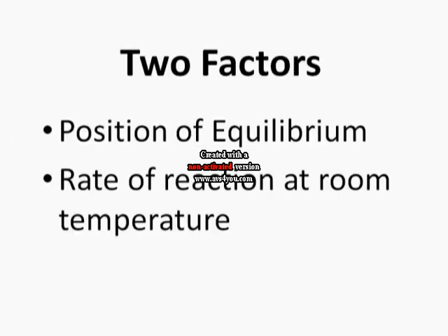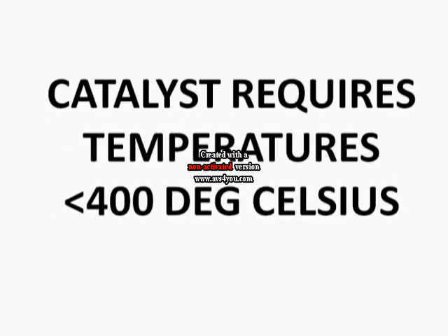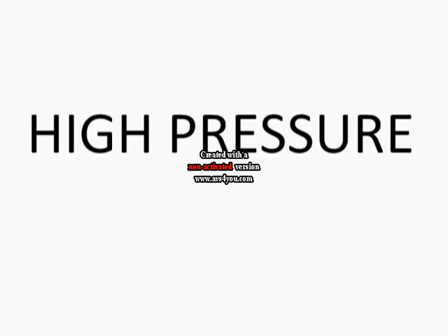As the temperature increases, the equilibrium is shifted and hence the amount of product drops dramatically, according to the Van't Hoff equation. Thus, we can suppose that a low temperature is to be used and some other means to increase rate. However, the catalyst itself requires a temperature of at least 400 degrees Celsius to be efficient. Therefore, pressure is the obvious choice to favor the forward reaction.